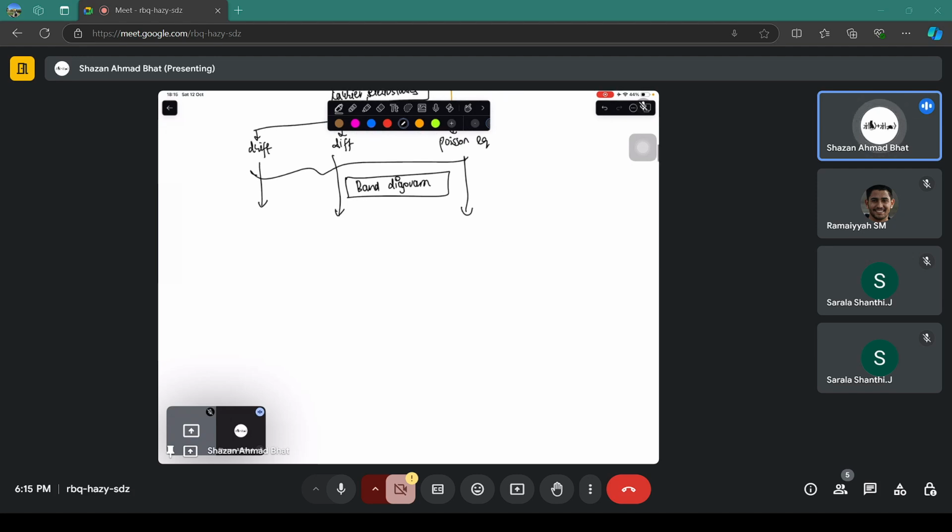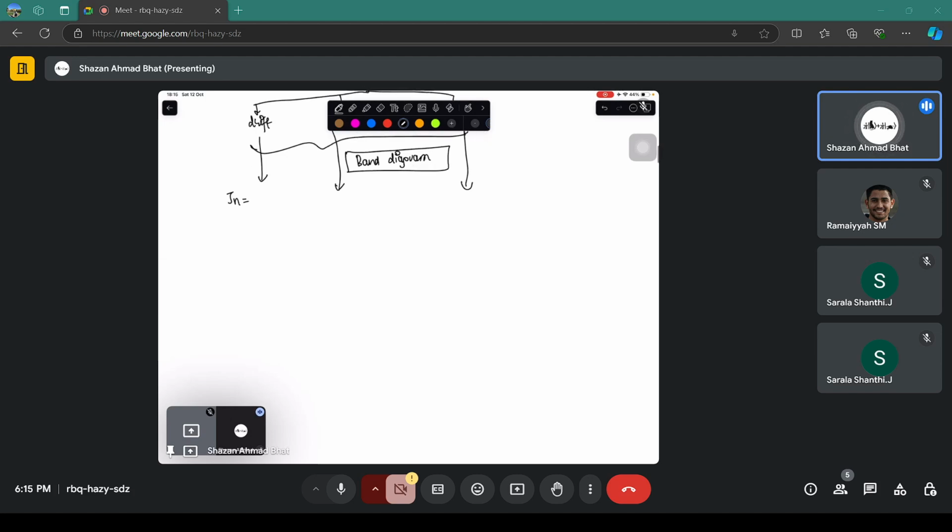You know, if there is an electric field present, then there is electron drift and hole drift. In presence of the electric field you see the drift current, because of the drift of the electron due to the drift velocity. The drift velocity is proportional to the electric field, and mobility is a proportionality constant here. And you have the drift current because of it, which is equivalent to q times n times the drift velocity, and you can write it as q n times the mobility times the electric field, which is the drift current density of the electrons.